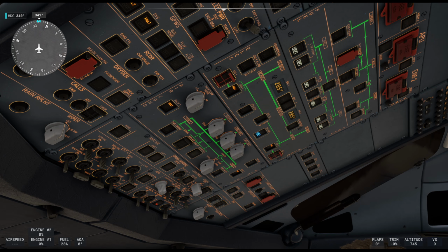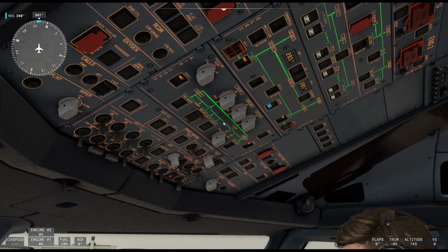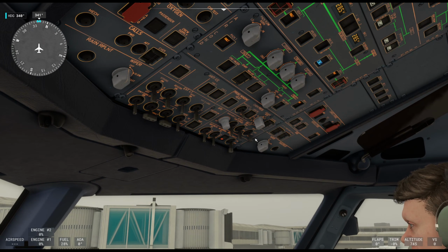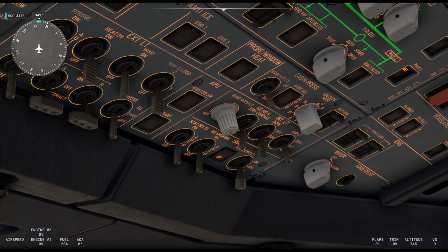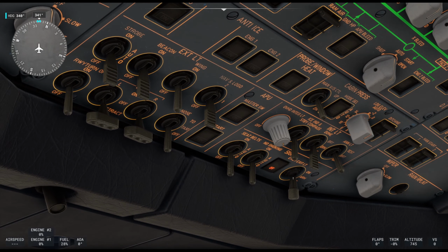And then we'll keep coming down. Here's our air conditioning. We don't need to worry about that right now. And then our lights. So we're going to start with turning our emergency lights, these are the emergency exit lights in the cabin, to arm. We'll be turning the no smoking light, which also could be a no portable devices light, on.